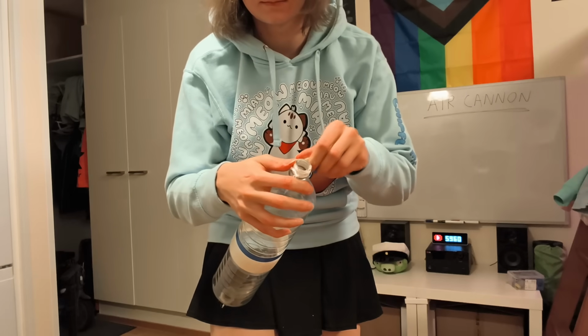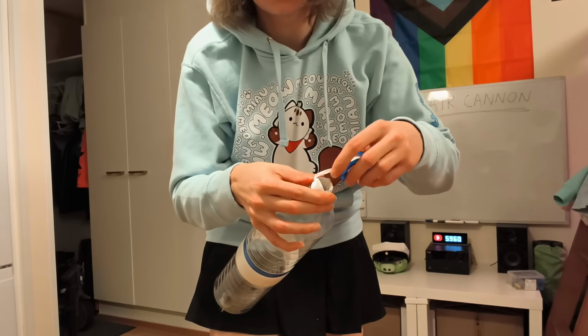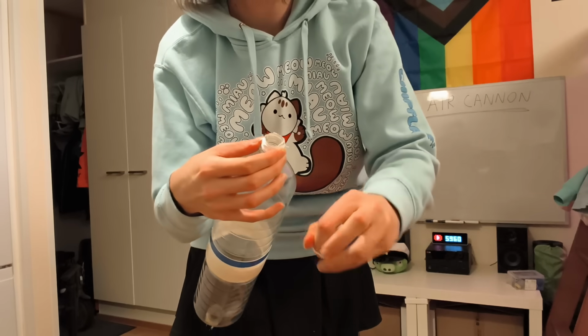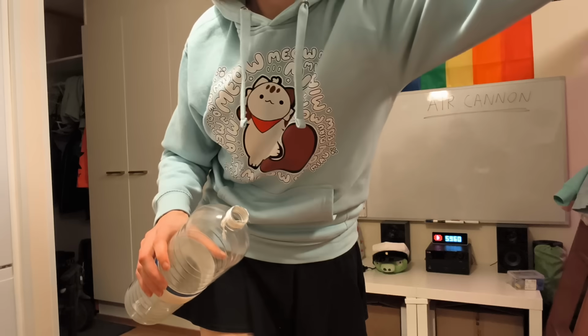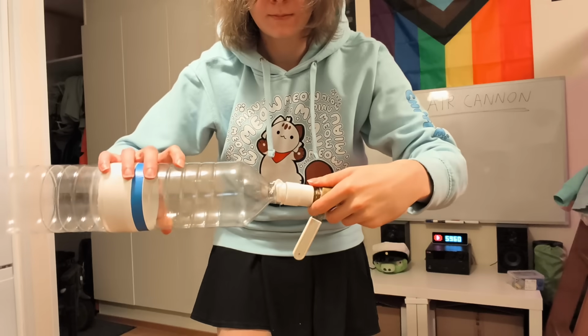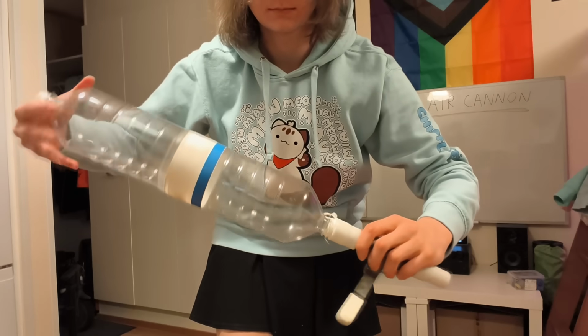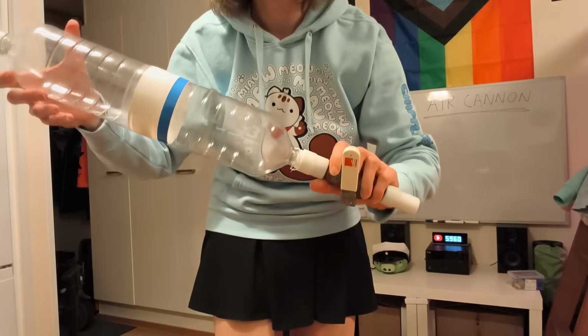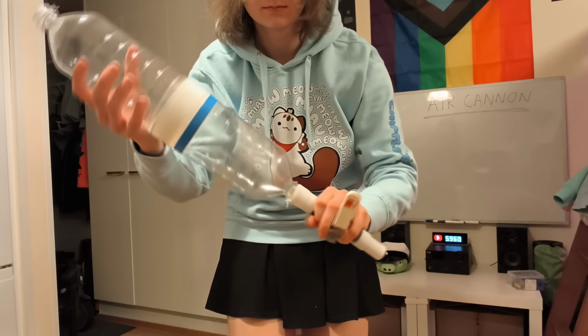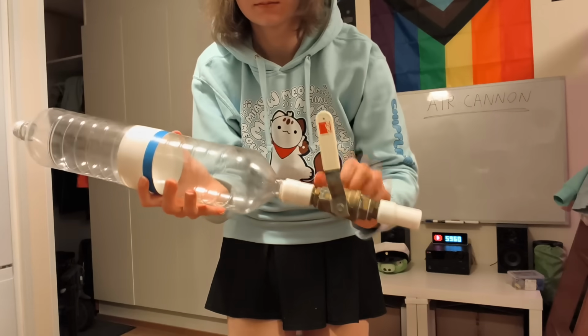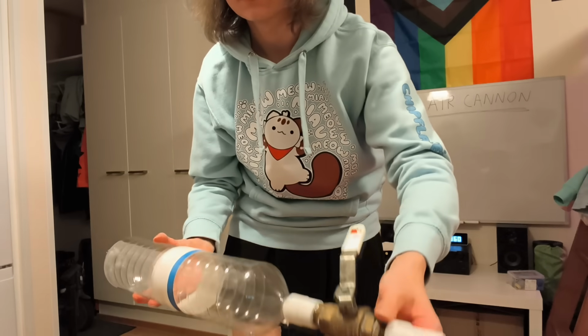I used some Teflon tape, which I put around the threads of the bottle to seal them, to make them airtight. Because the valve can be screwed onto the air tank, it means that the system is modular, which is useful if the air tank or these 3D printed parts break or something. It's also convenient because I can just screw it off if I want to add more air tanks or change the valve.